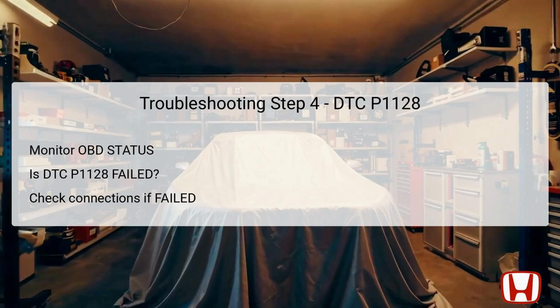If it indicates a status of failed, then proceed to step 7 as the issue is not resolved. A passed status suggests that the system is functioning correctly at the moment, but does not guarantee a permanent fix. In case of past, you should check for poor connections or loose terminals at the MAP sensor and the ECM/PCM, engine control module, powertrain control module. Poor connections here can hinder signal transmission, potentially leading to recurring DTC P1128.